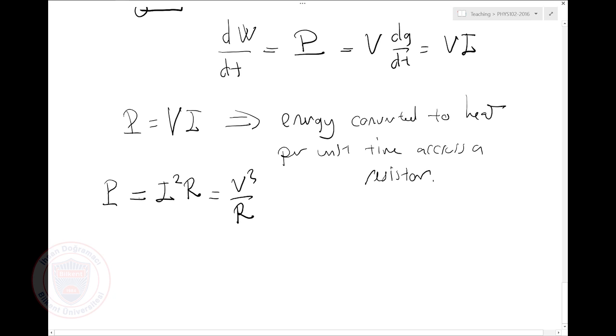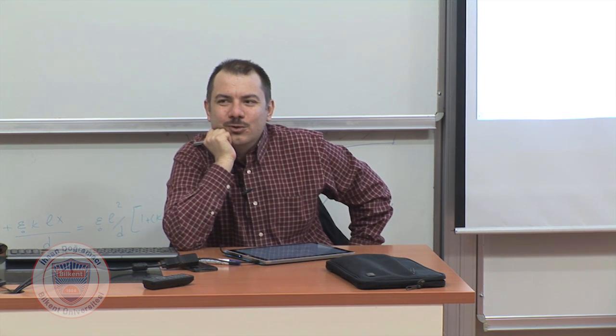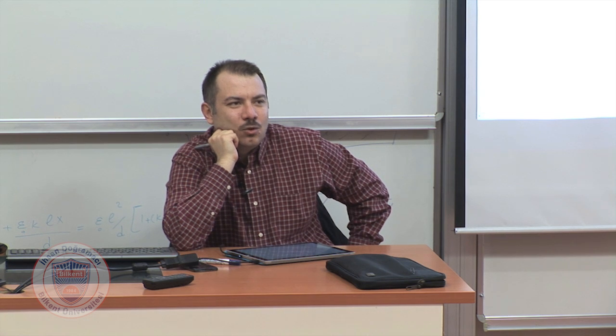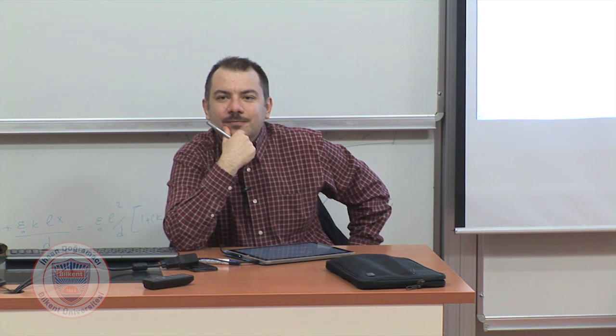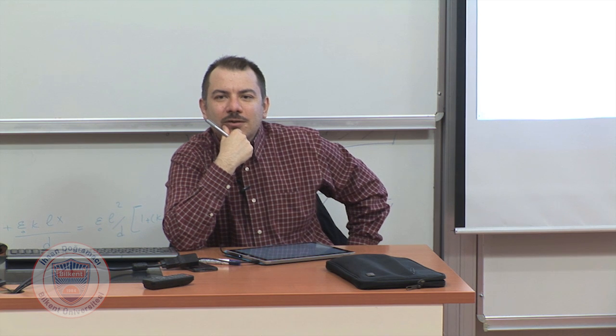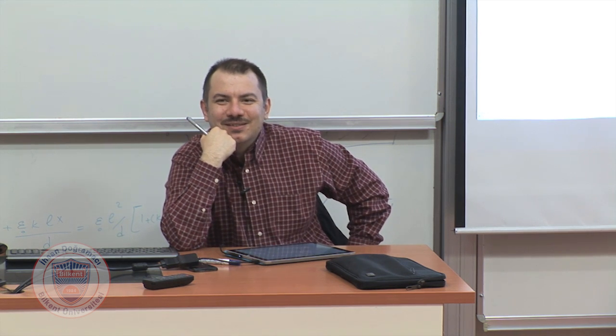And this may be a curse, right? This energy being converted into heat may be a curse. A lot of the energy generated in hydroelectric dams and other generators in Turkey is being lost on the transmission lines. We are literally heating the air, okay? Because Turkey's power transfer structure is quite old and not very well planned. Almost 20% of the energy generated in our plants is lost to this ohmic heating on transmission lines. That's terrible.